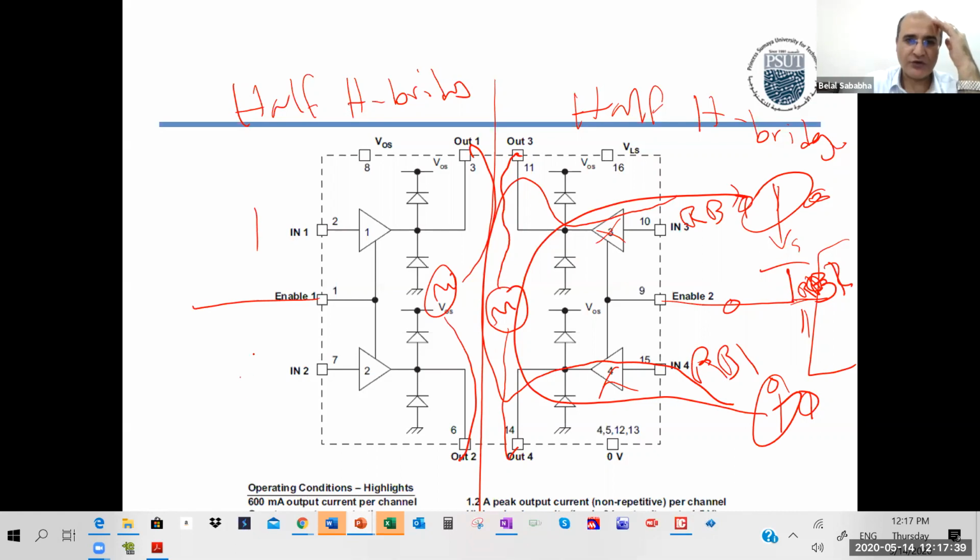Enable 1, 0 to turn in one direction, 0, 1 to turn in another direction, and 0 here to disable and turn off the motor. So you can use half an H bridge to control 2 motors, but you can control them on or off.